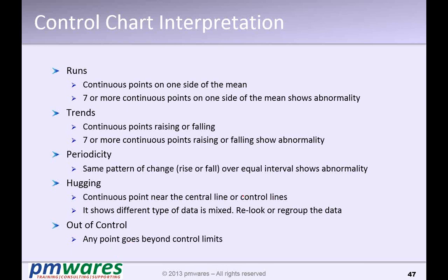Okay. So control charts help us to maintain the sanctity of the process. Anytime we see some kind of pattern, we stop the process and look into whether everything is fine. A pattern normally shows that one of the machines or one of the value-adding components, either a human or a machine, is causing some kind of problem.